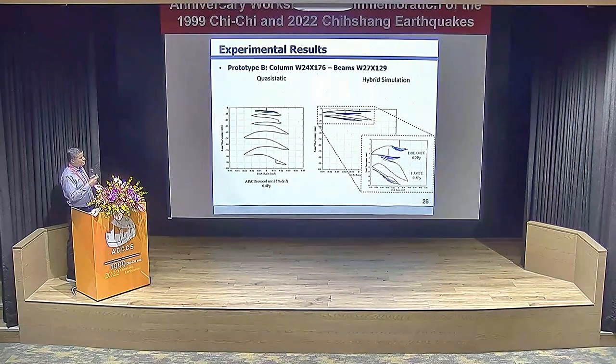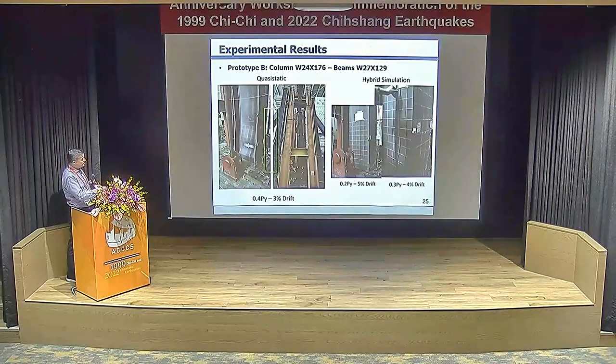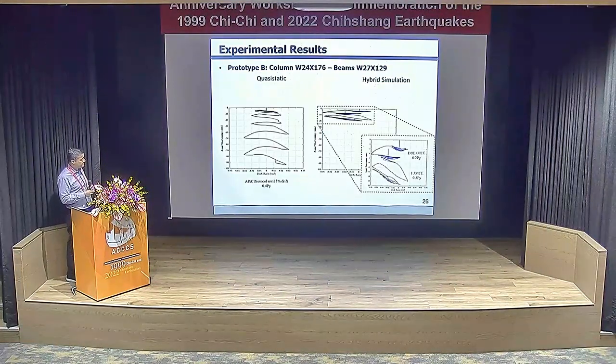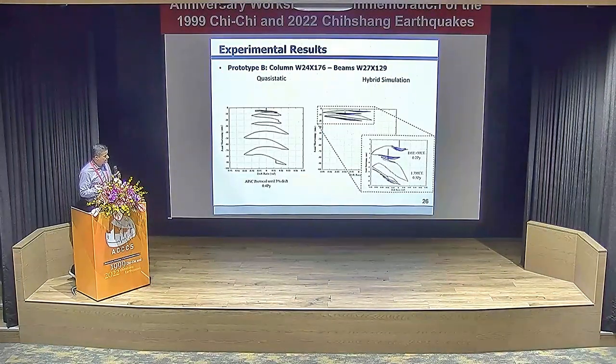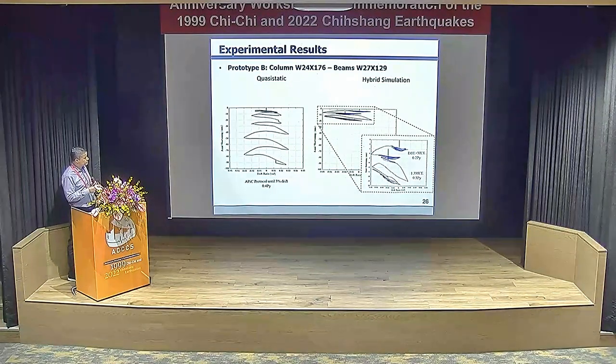Again, we couldn't correlate really load to load in some of these tests because one of the parameters we did adjust in real time was even the axial load, because one big problem was with this global buckling phenomenon going on here. This carried up to the top loading beam, and the whole thing started to tilt. So we had to be very careful about the level of drift and level of axial load that we're applying to the specimen.